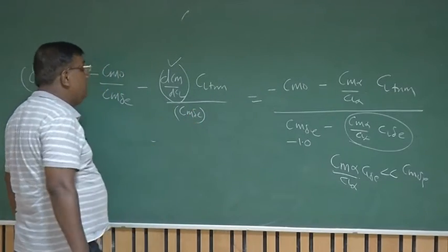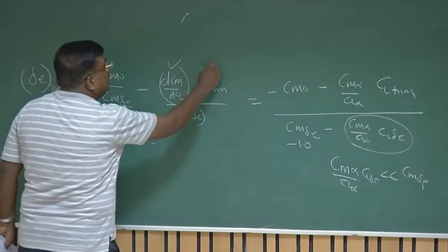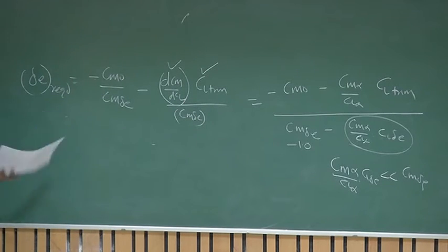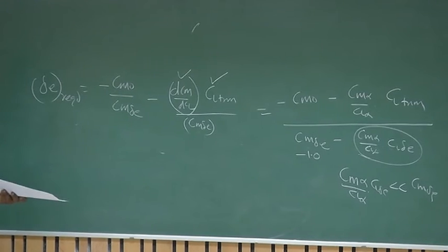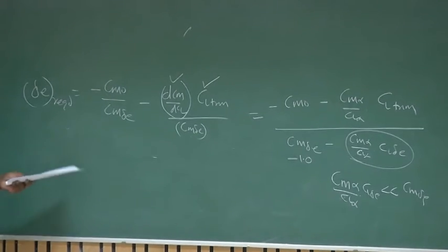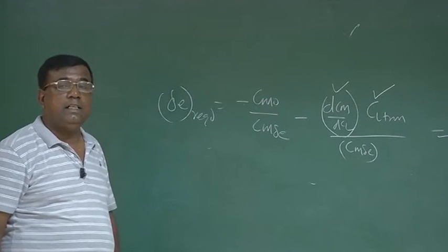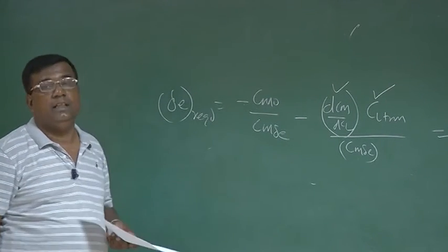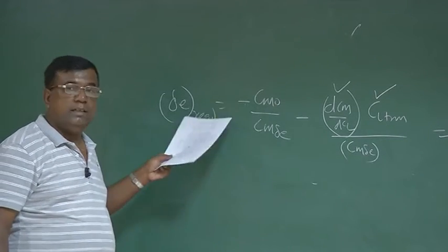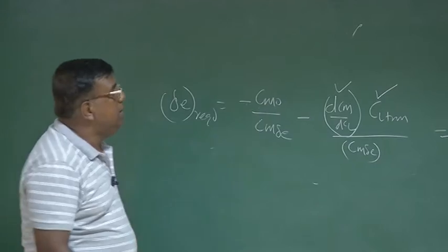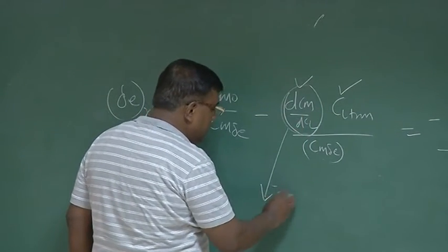Cm delta E is here. What is the meaning? Meaning is, tell me what CL you want to trim, then immediately this will give delta E required. But then, if delta E required is coming 50 degrees, 45 degrees, you say, oh, sorry man, I cannot trim your aircraft at that CL because delta E is coming very, very high. Okay, so there is a limit that will be set by this. And what is this dCm by dCL? This is nothing but static margin, remember?